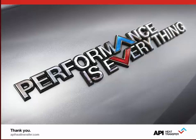All right, thank you. Another question here. Any application where you cannot use plate and frame? Yeah, for sure. There are a lot of applications where you cannot use them, especially if you go to a very dirty process, because then you do not have a plate heat exchanger, then you have a filter. But you just filter with the plates, right? So this is not what you want to do. You want to exchange the heat.